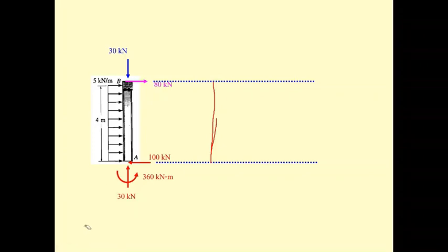The line is not vertical. Let's take this one out. You may draw like here, and you start to draw from 0 meter to here is 4 meter, and then we have what? We have the 100 Newton. So this one is up, and it's up for 100 Newton, and then the slope here is going to be minus 5.